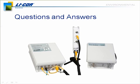So with traditional closed path analyzers, once you start to see some accumulation of debris, your signal drops off really quickly, and so you're required to have some pretty tight particle filters, usually on your inlets. As Dave talked about earlier, those particle filters are going to potentially attenuate some water vapor fluxes, and they're definitely going to increase pressure drop for the system, which means more power. So that's another key difference with the instrument.